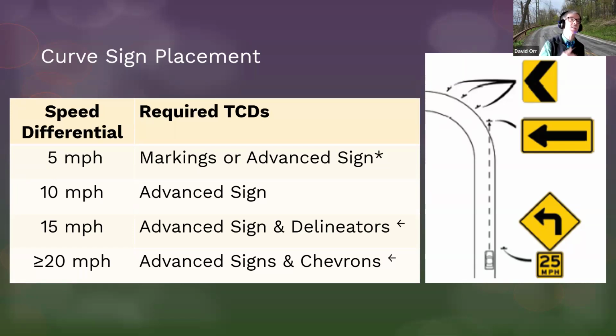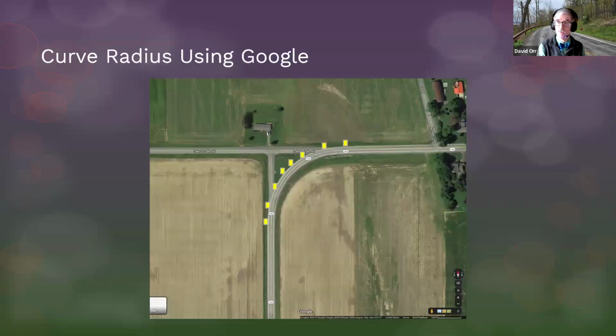Now, here's a question here. If my only choice is 80 or 100-foot spacing, can I interpolate? Well, of course you can interpolate. That's a starting point. Remember, it's a standard. The sign spacing for the delineation is really just a starting point because you're going to have to modify things. As a perfect example, let's look back at our curve. So I plopped on here somewhere the chevrons would need to be.